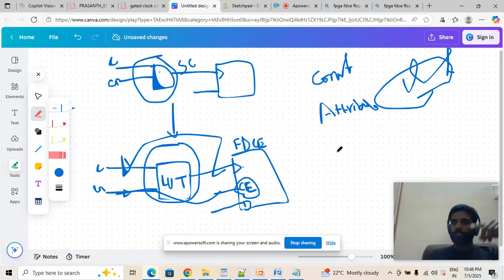And there's one more option: the synthesis tool settings. My tool will give you an option to enable gated clock conversion. If you enable this gated clock conversion, the tool will understand that some clocks are going to be there, so it needs to consider them as clock gating and convert this logic. So you don't have to do anything manually.